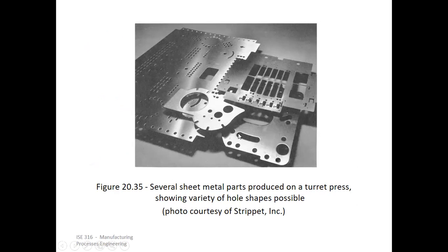Slots, if you observe, this is not a straight slot, right? A kind of curvy slot is possible, and you can see the amount of space it is left here, because once you press or try to take out the material here, and the next here, you are having a lesser gap in the two, so it will not be that easy to create that. You have to have a system wherein there's some supporting below this that has to be perfectly aligned, right?